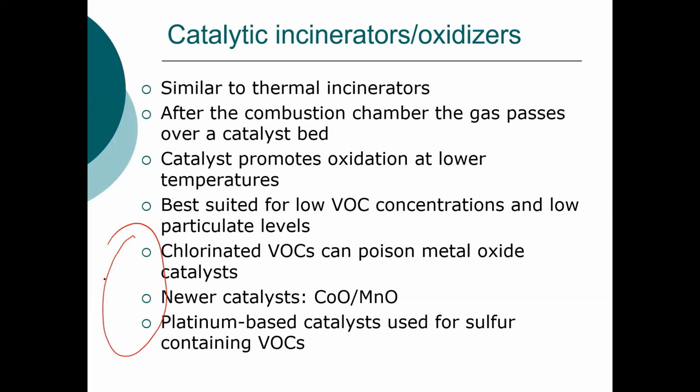And you're proposing to use a stripping column, the absorption, to transfer those chemicals from the groundwater into the air phase, and then use a catalytic incinerator in order to oxidize those chemicals, the benzene, the toluene, the tetrachloroethylene.